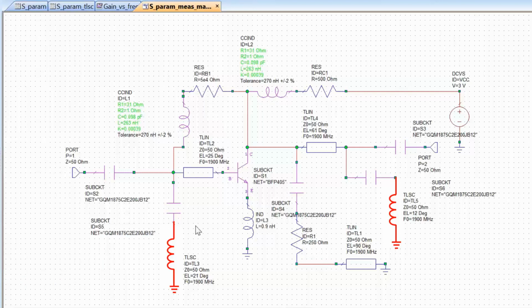Now, if in a branch you have an inductor in series with a capacitor, guess what's going to happen? You're going to have resonance. So there's going to be frequencies at which the capacitors and the short-circuited stubs, which behave like inductors, will resonate, and hence you will have a very low impedance path to ground, which will sink the high frequency energy at that particular frequency at which resonance occurs. You don't believe me, do you? Well, let's prove it.